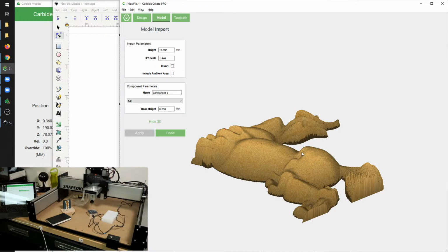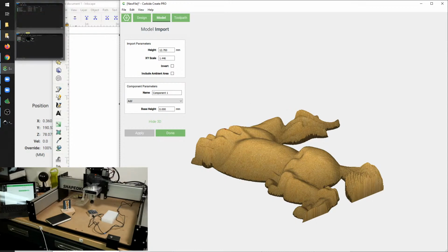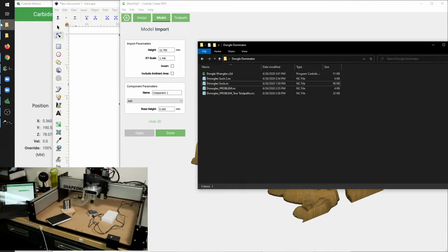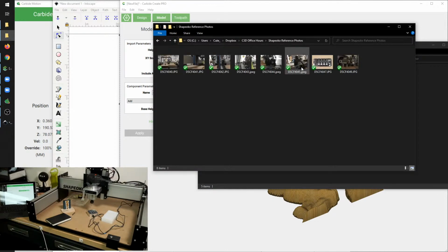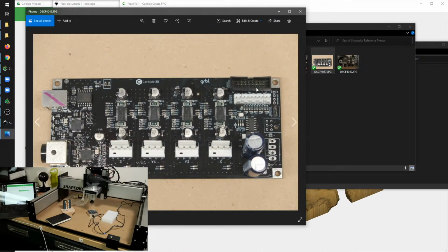Is there going to be an option for an RPM-controlled spindle like the Nomad, only stronger? Maybe not. The problem is you need a PWM signal to be received to control that. So you'd have to go full VFD spindle. And let me see if I can find a reference. On the control board, there is a plug for a VFD spindle, or well, for PWM control.